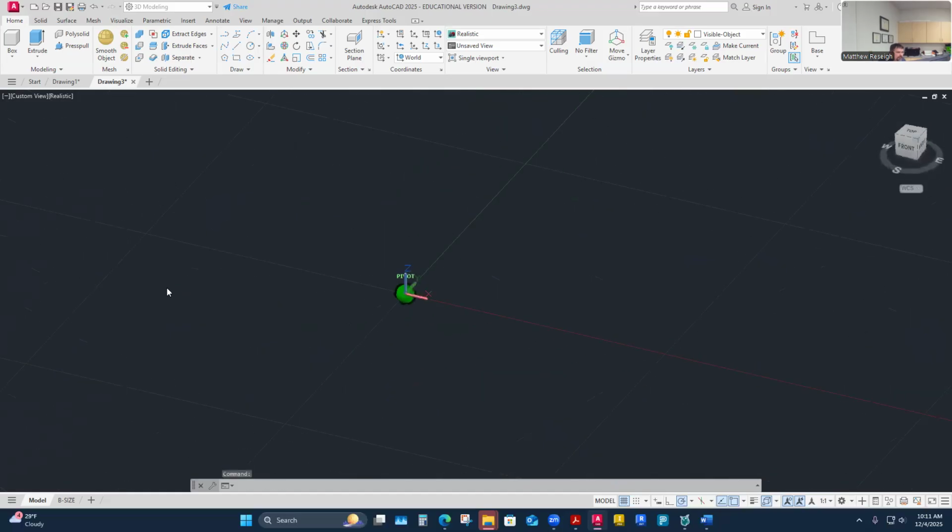It's good practice just to look at a UCS and do that. You've got to be looking at something. If you're looking at a grid, you can at least see how it moves around. But you definitely can get backwards. If you flip the grid upside down like this, you can get lost. Your navigation wheel helps you a lot. I look at my navigation wheel a lot.